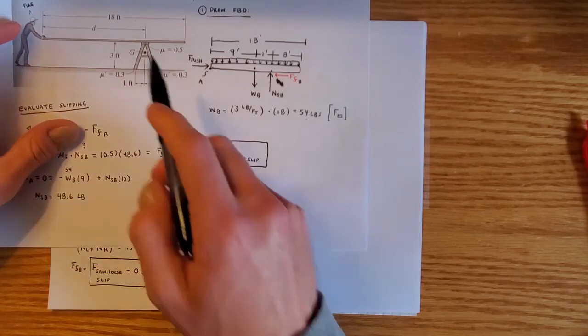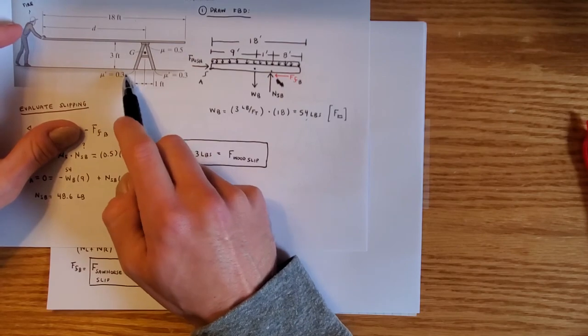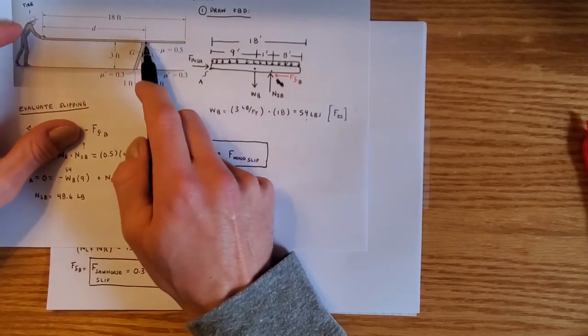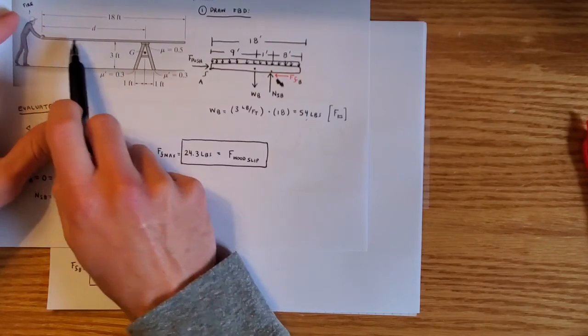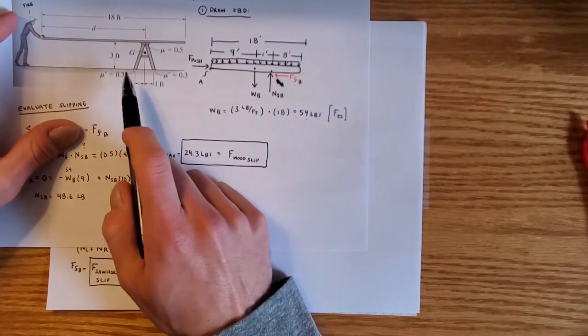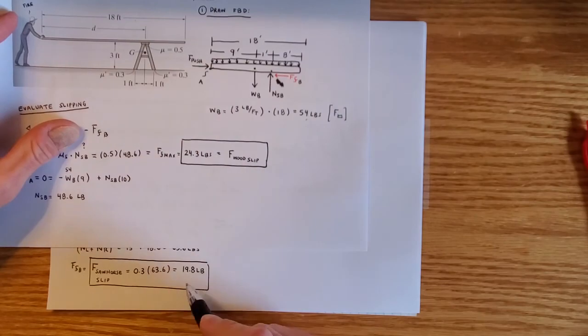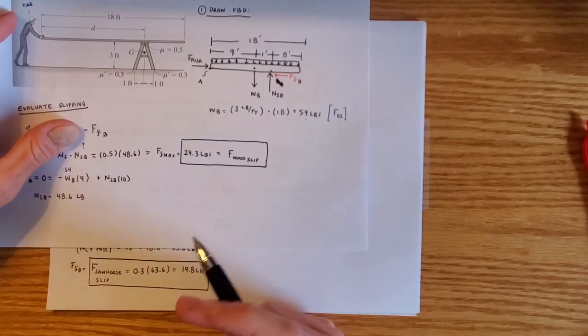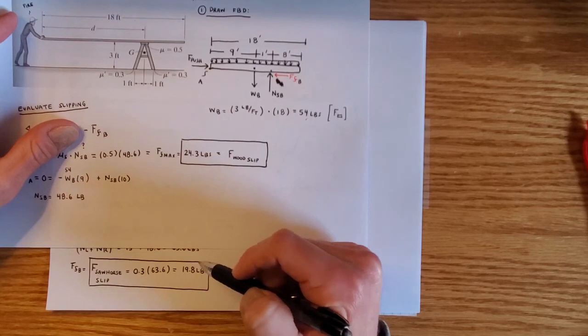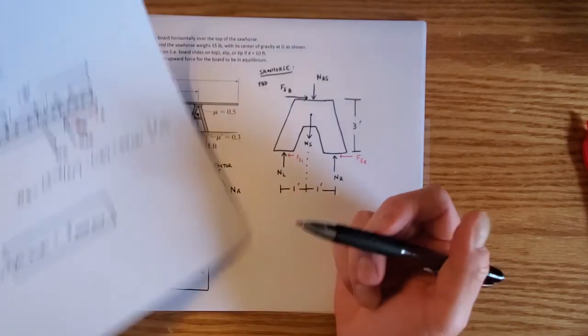One of the reasons we can see this is that the ground has less friction than there is between the board and the sawhorse. So before the board slides, the whole system starts to slide because the ground has less friction. So right now this is our limiting factor, but the question will then become, maybe our sawhorse tips before it slides. So that'll be the next condition we check.